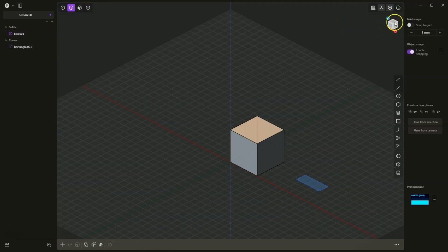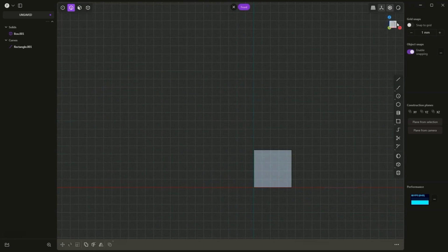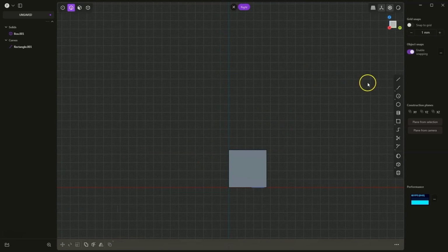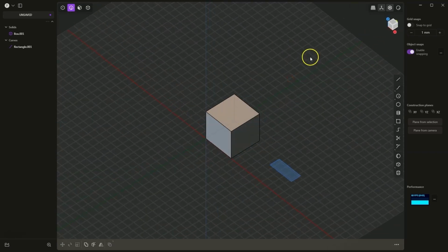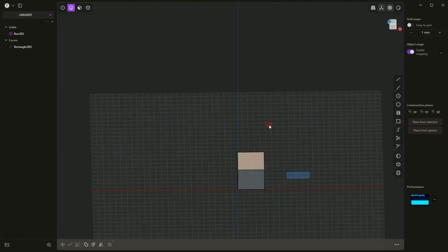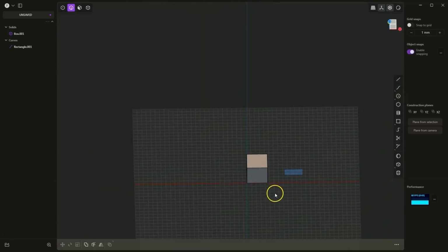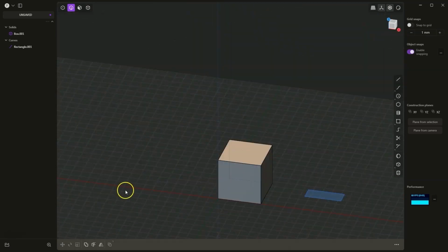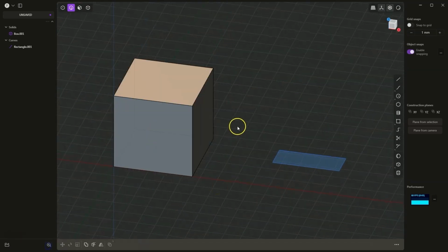And here we have a box, and by clicking on the faces of this box, we can align the views of the coordinate system planes. If, for example, we want to draw something in the top view, we can click on this face, and we will be switched to the top view. Now, if I press the mouse wheel, I can rotate the solid. By pressing the mouse wheel, we can rotate the view. This automatically disables the view on the construction plane, and here we have a button that enlarges the geometry.